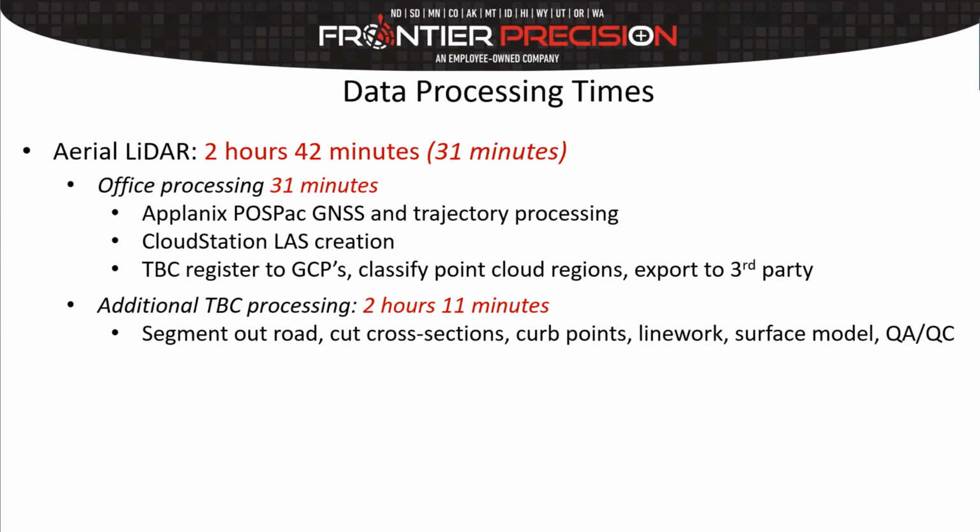Moving on to aerial LIDAR. So processing the data here took us 2 hours and 42 minutes to go all in with TBC, and 31 minutes to just get it out to third parties. So that includes post-processing the trajectory and GPS in Planix, creating the LAS files out of CloudStation, registering it to ground control in TBC, and exporting to third party. And then to create the line work and the surface model and things like that in TBC took about another 2 hours and 11 minutes. So start to finish about 2 hours, 42 minutes.